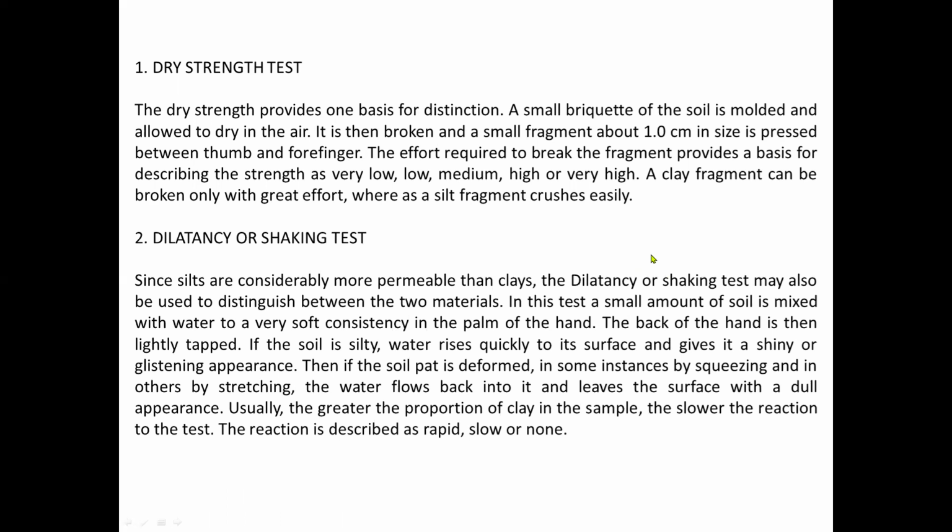Then, if the soil pat is deformed, in some instances by squeezing and in others by stretching, the water flows back into it and leaves the surface with a dull appearance. Usually, the greater the proportion of clay in the sample, the slower the reaction to the test. The reaction is described as rapid, slow, or none.